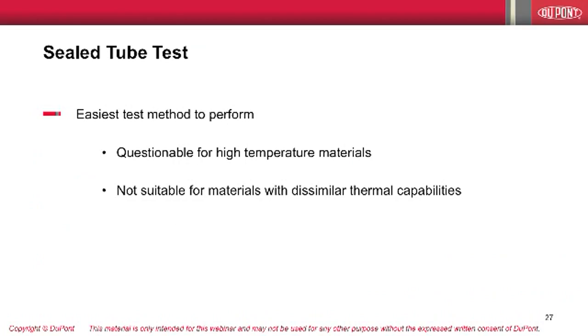However, its application to high temperature materials is questionable, since the liquid sees the high temperatures and is certainly damaged. It is particularly unsuitable for systems with components that have broadly dissimilar thermal capabilities, such as Nomex and mineral oil.